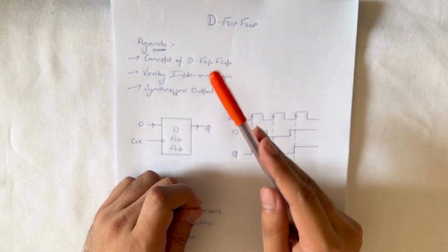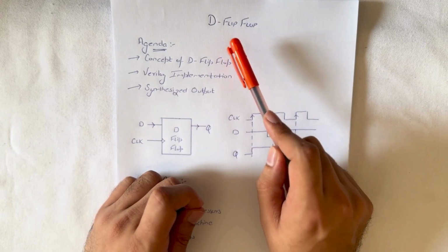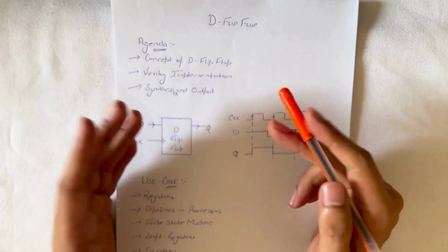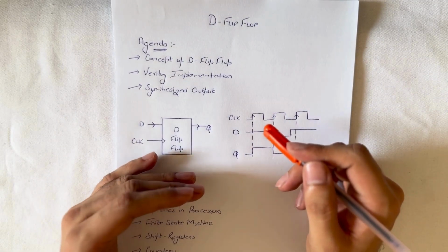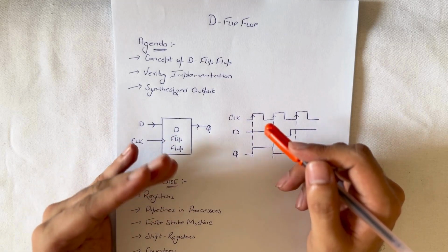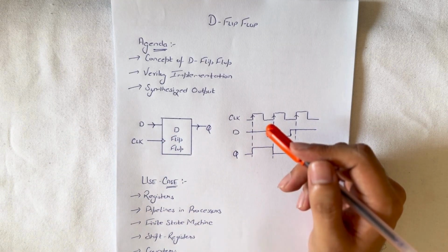In today's video, we are going to understand what a D flip-flop is, why it is important in VLSI design, and then we will write the Verilog code for both synchronous and asynchronous D flip-flop. Finally, we will also look at how the design appears after synthesis.